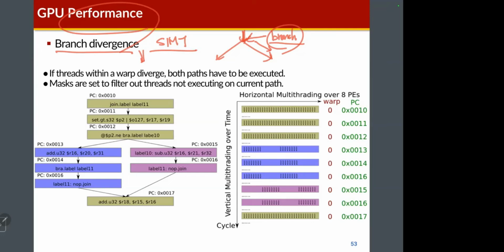I said the GPU uses a warp as a group of threads, and in NVIDIA GPUs a single warp includes 32 threads. Now, how can you support diverse branch instructions? Why does the GPU group threads into a warp? Because the GPU hardware looks like a SIMD architecture, and we can increase the efficiency of the SIMD architecture if multiple threads execute the same instructions.